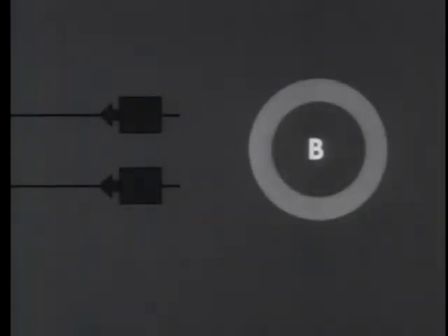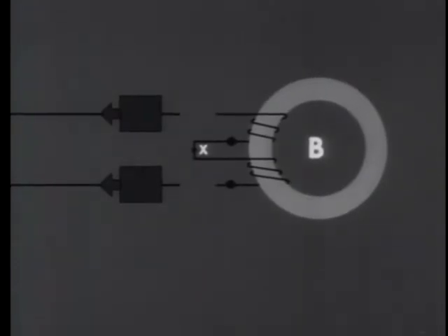First, we'll wrap two small windings around core B, an upper winding and a lower winding. The polarity is the same in both cases as the dots indicate. The two small windings are joined together at point X, and this gives us the split winding from which this loop gets its name. All that remains is to connect the split winding into the circuit and provide it with an outside source of current.